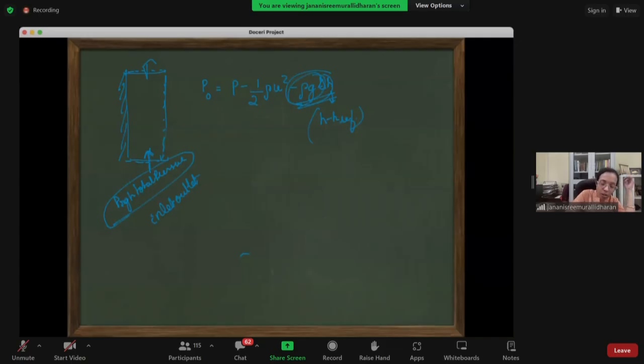Now, what values of pressure will you give here? As you're moving up, there might be some influx also, right? So here you will give something called a fixed flux pressure, because if your code is calculating some u value here, then your pressure will get adjusted according to this velocity flux.